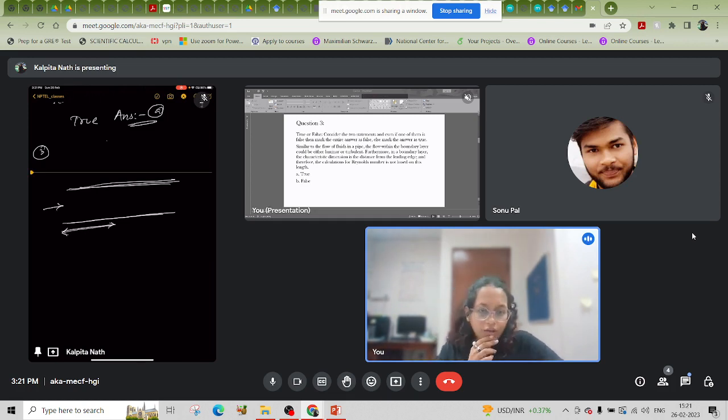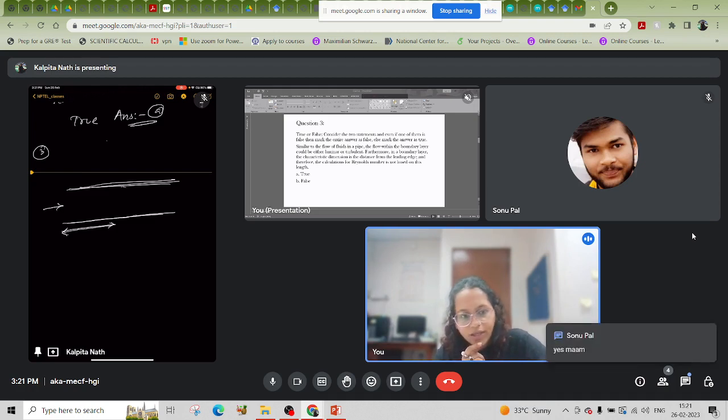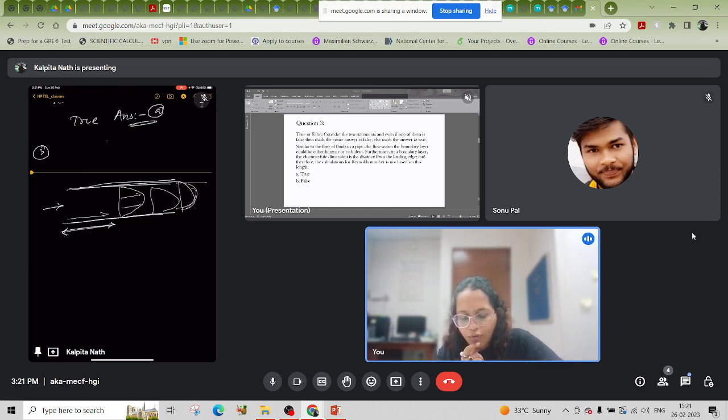You understand hydrodynamic entry length, right? That is where the boundary layer won't be fully developed in that region, and after that region, boundary layer will be developed like this. So there will be some distance up to which the boundary layer won't be developed. After that, boundary layer will be developed, but flow will be either turbulent or laminar. It won't be both.